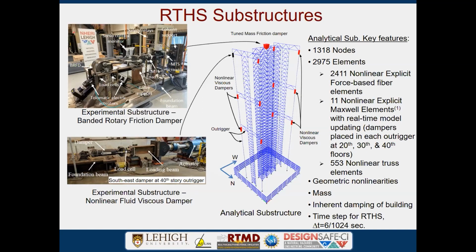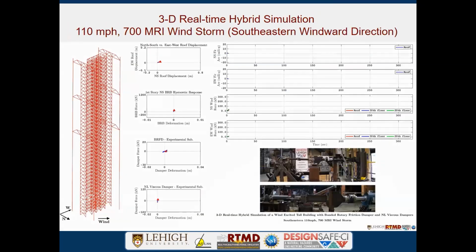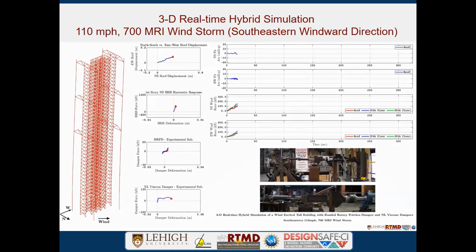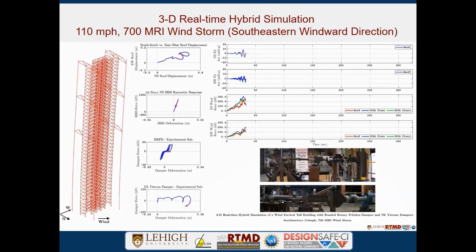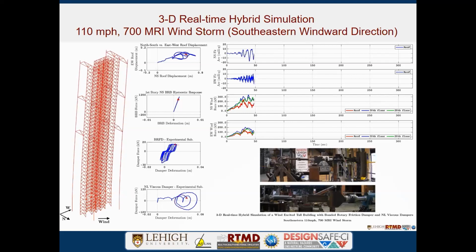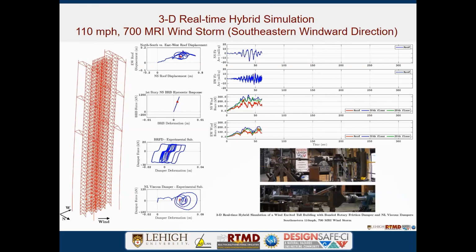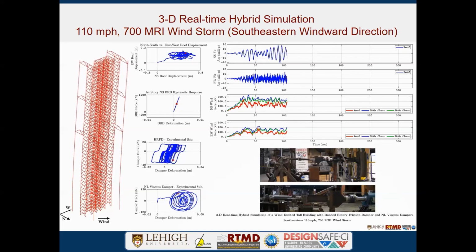Now here is the video of this structure under the wind loads. So the 3D wind loads we're applying are from the aerodynamic tests we did in FIU facilities. And the top left graph is the top view of the structure. The wind is blowing at 45 degrees. You can see this structure is leaning at its 45-degree angle, and also has some vortex shedding effect.